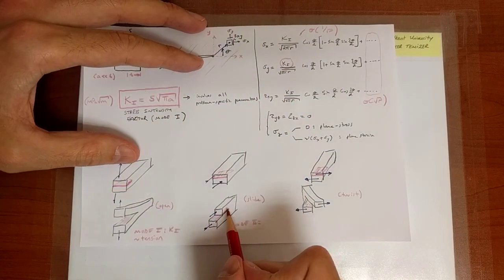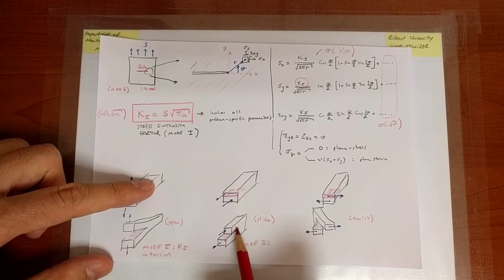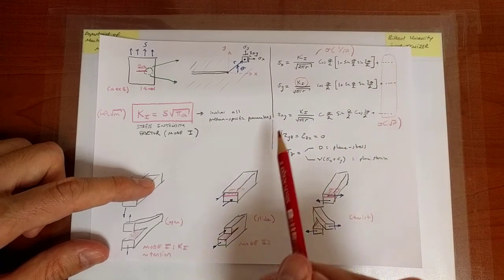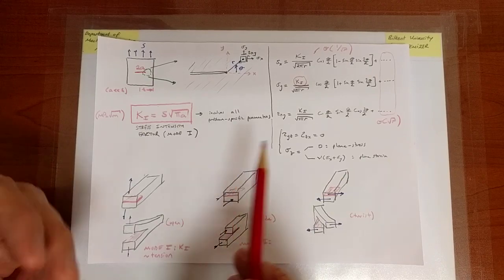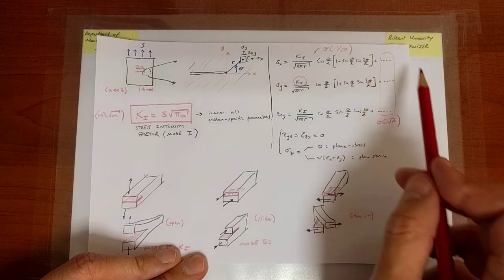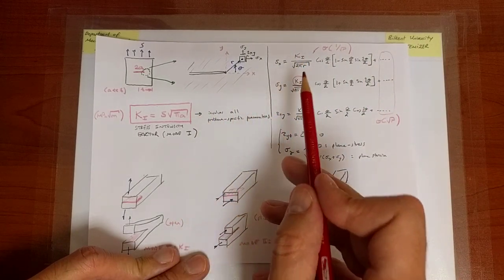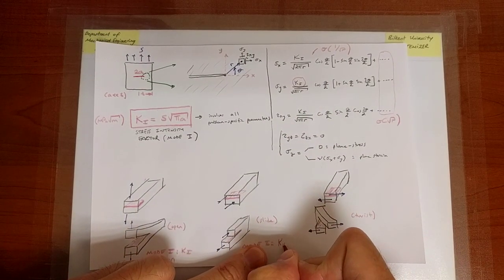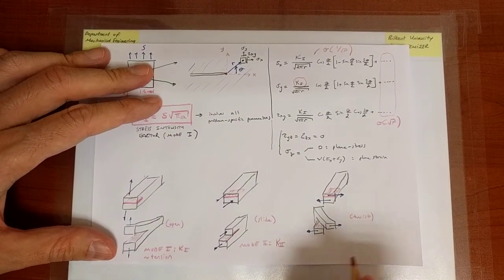And eventually, if we try to depict mathematically the stress field in the vicinity of the crack tip as a result of that motion, it turns out there are expressions which arise, well, not in this probably complicated geometrical scenario, but in a scenario that is comparable to that geometry, the stress field would be very similar to these, except that instead of K1 as a problem-specific parameter, there would appear a K2, and their definitions are very similar to the definitions of K1. We're going to see how they're defined eventually when the time comes.